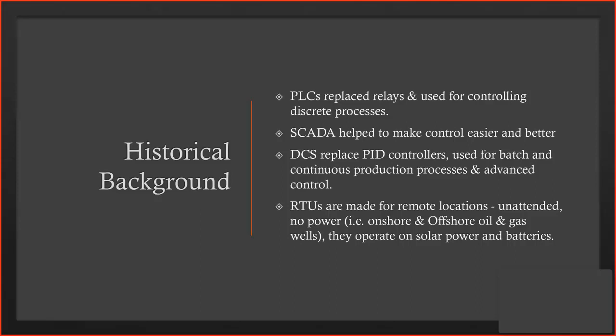You must have supervisory control and data acquisition. If the sensor doesn't sense the right value and it can shut down your valve, there is nothing you can do if you don't have SCADA. What SCADA gives you is an edge over those sensors and valves, to control them from software, like a human machine interface, a graphical user interface. So that's the advantage of SCADA. Now you are not that blind, you can control it in a better way.